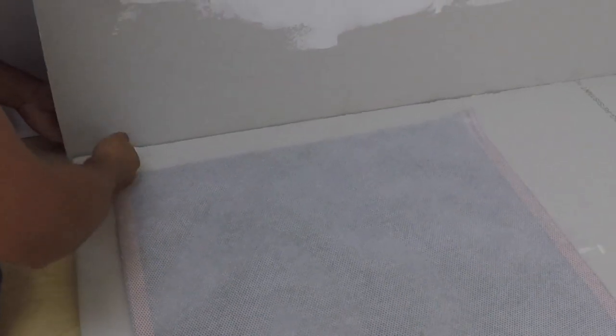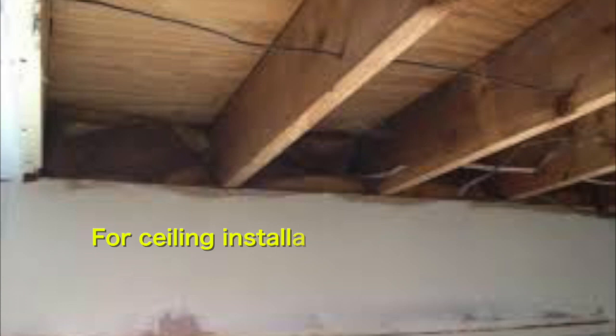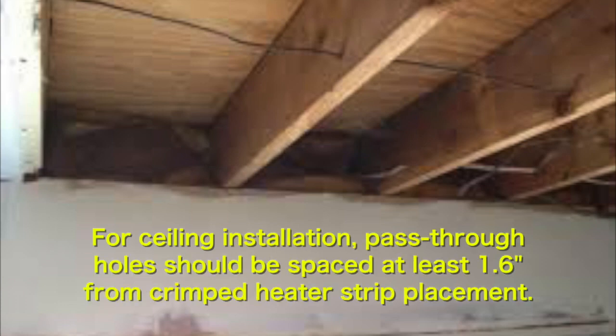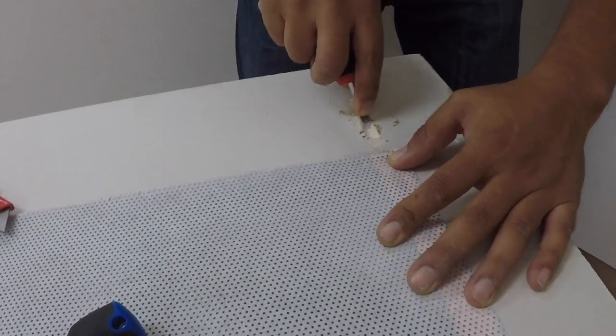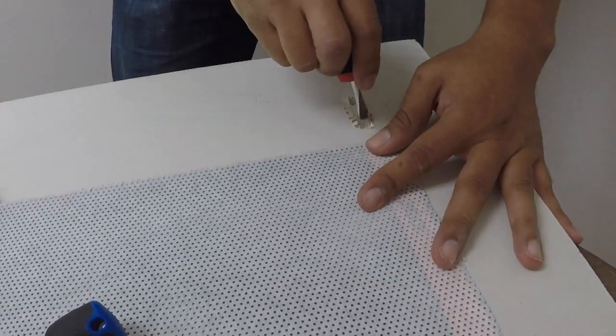Before any plaster is set, drill pass-through holes into drywall and studs to allow for routing the heater supply wire. For ceiling installation, pass-through holes should be spaced at least 1.6 inches from crimped heater strip placement to allow bending for the heater wire. Additionally, small indentations can be made into drywall in order for flush installation onto ceiling surface.